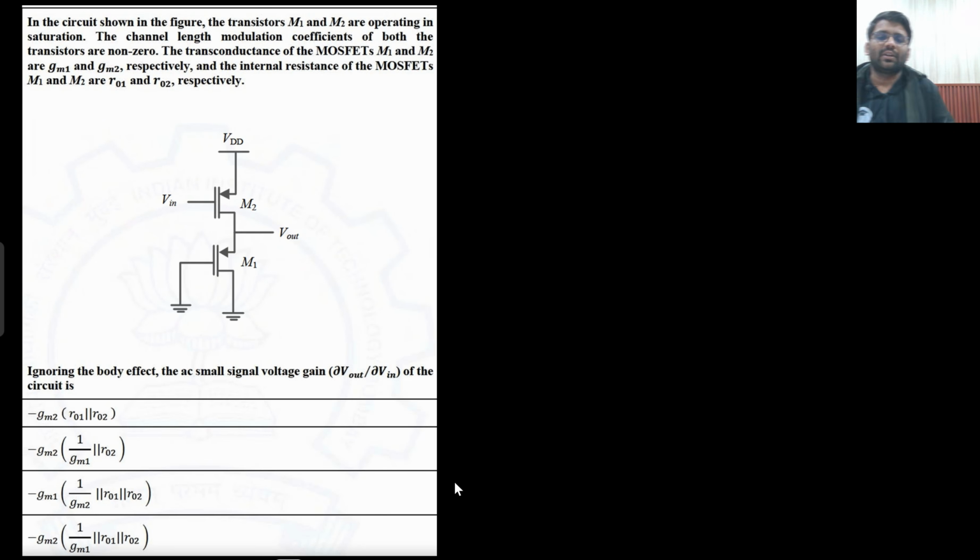Now another very small thing. There is a potential V. From this potential V, I current is flowing. So the value of this resistance R is V by I. Similarly, if from this potential V, Gm V current is flowing, the resistance R would be 1 by Gm. Well and good, I will be using it somewhere. Let's get started with the question now. Small signal gain we need to find out. We always have to move from V1 to V0.